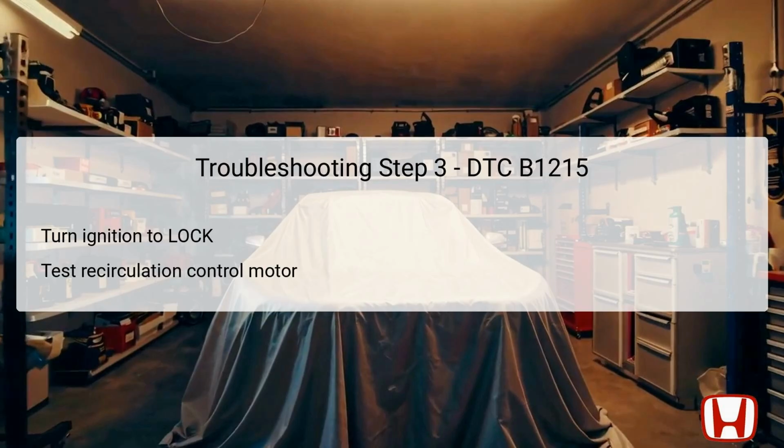This involves isolating the motor from the circuit and applying power to examine its operation. A functional test will reveal whether the motor operates correctly when given input. If the motor is determined to be working as intended, technicians can proceed to the next step. However, if the motor fails to operate, replacement of the recirculation control motor becomes necessary, addressing the root cause of